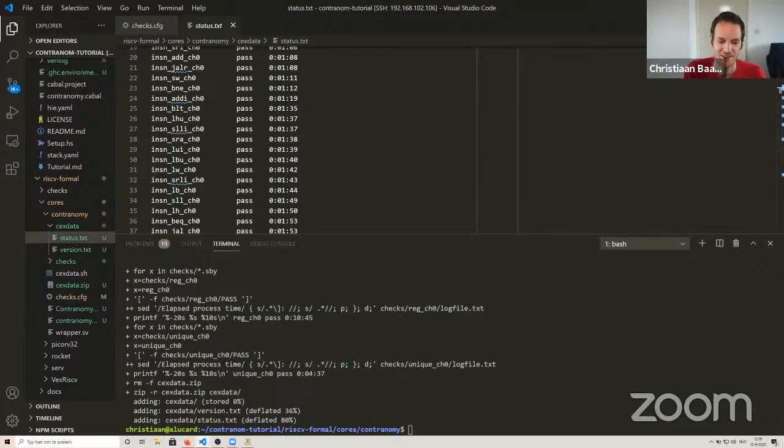What I didn't formally verify was that I was adhering properly to the Wishbone interface, or the protocol, which basically says that after an acknowledge has arrived from the slave, you're supposed to deassert the cycle and strobe value for at least one cycle before you assert it again.